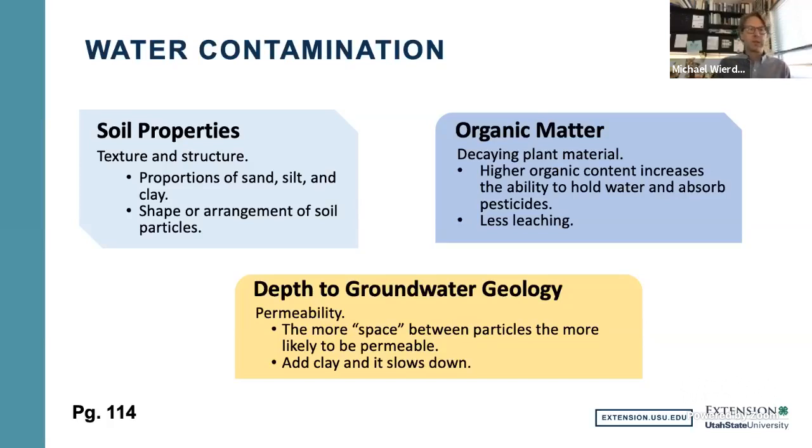And then, of course, the depth to groundwater or geology plays in. The permeability: the more space between particles, the more likely it is to permeate through the soil. The addition of clay, again, will slow that down. So knowing the soil structures, what kind of organic matter, and your geology will all help you avoid contaminating water when making applications.